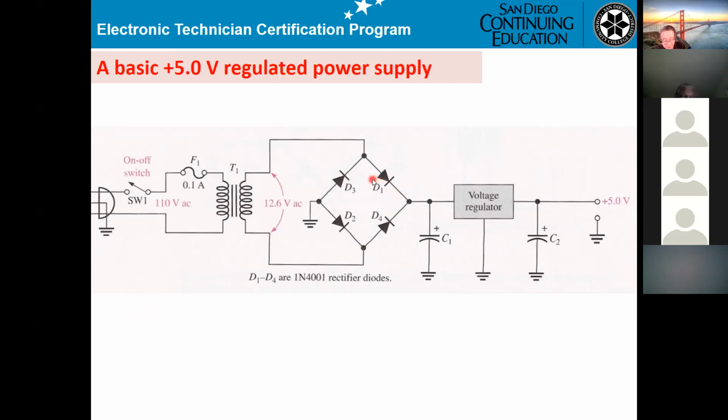What you need to do is test again to see if you can get 5 volts here or the ripple working or not. If it's working, that means you did a good job. You fixed it. However, if you replace D1 and it's still not working, you say replace D2, D3, D4, or replace this guy here, or this guy here. That means you replace everything, then it must be working.